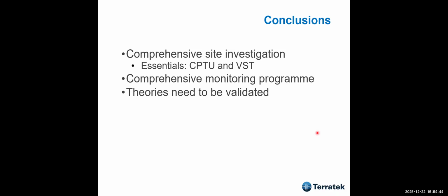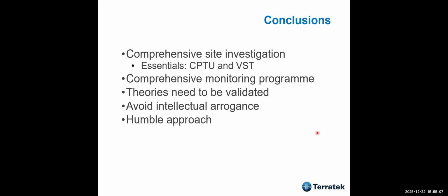Theories have to be validated. Do not use any theory before it's validated against field trials. Avoid intellectual arrogance, when someone comes and says, because I know how to calculate this, let's try a new method which wasn't tried before, like some I have shown you here. Have a humble approach in soft soils, okay? And try trial embankments for larger projects. This is very, very important, okay?